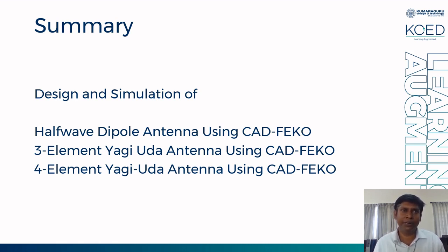So after fabrication, you need to validate, right? You need to test and validate, right? For that also, in our department, we have the facility, okay? Up to 16 gigahertz. If you are trying to design antennas up to 16 gigahertz, you can design it, fabricate it, and we have the vector network analyzer to test it and validate it. Okay, so what you can test here is the impedance characteristics, that is S11, then VSWR. So these things you can test here, reflection coefficient S11, VSWR results. You can test it using the vector network analyzer available, and you can validate with your simulated output.